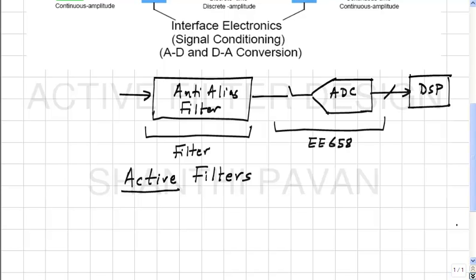Now, time constants are all of the form RC, L by R and root LC, correct. So it follows that if you want to realize filters in the low kilohertz to several hundreds of megahertz range, the time constants that will be involved will be of the order of microseconds in the megahertz range to several milliseconds in the kilohertz range.